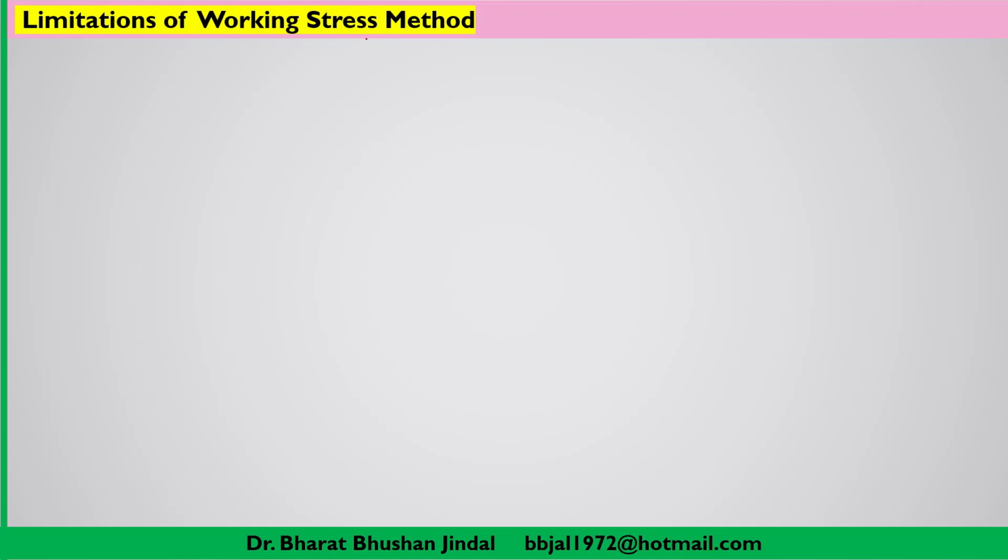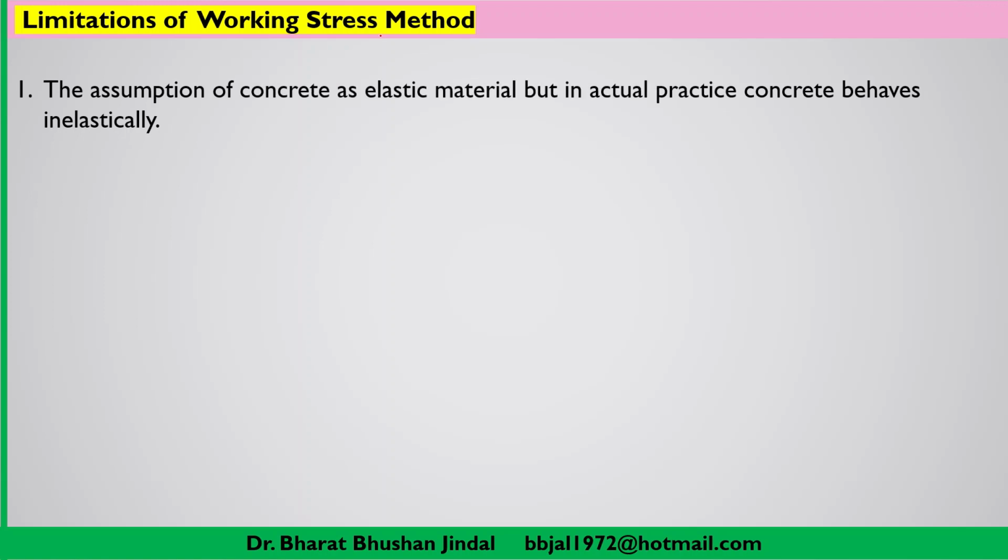Now let us discuss a few limitations of the working stress method. The very first limitation is that we are assuming in the working stress method that concrete is an elastic material. But in actual practice, as we have discussed in lectures 1, 2, 3, concrete is not an elastic material. It possesses inelasticity, so it is an inelastic material. So this is a drawback or limitation of the working stress method.